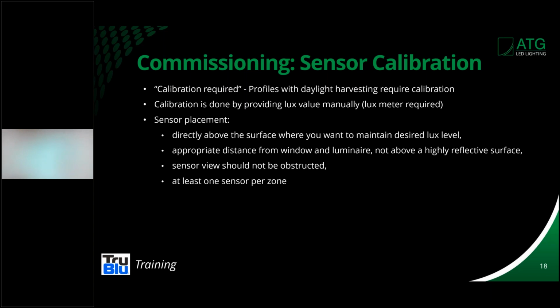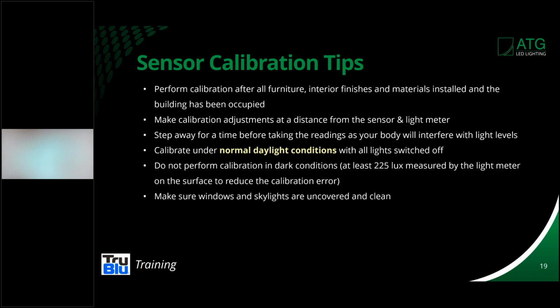So these are just things that you have to keep in mind as you go through the commissioning and calibration of the sensor. Some tips here, all right? The calibration should be done after all the furniture, the interior finishes, and all the materials are installed, the way the building is going to be occupied, right? If you're doing this when the building is still under construction, you're going to get wrong readings because the surfaces would be much different when the building is finished. So you've got to make sure that the building is ready to go before you consider calibration.